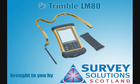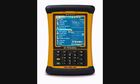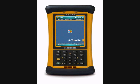We're going to take a look at the Trimble LM80 Layout Manager software as installed on the Trimble Nomad controller. So the first thing we'll do is launch the application by selecting the Trimble LM80 software from the Start menu. As soon as this opens, we'll be met by a graphical interface, which is where we're going to manage the jobs that we're going to be working on.